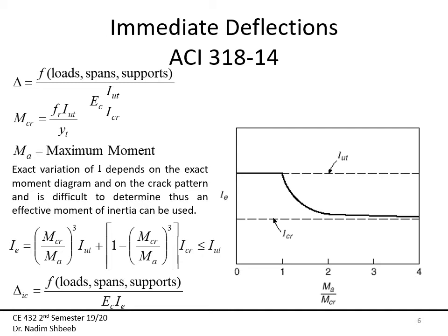Or the other part where this really becomes more apparent. So let's say you are designing the slab of a building, and then you use the H minimum technique, and you found out that for 90% of your slab you need, let's say, 25 centimeters, and for only 10% you need 30 centimeters or 31 centimeters if we're talking about slabs.